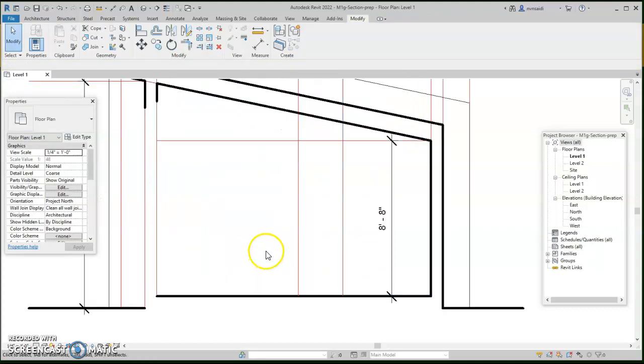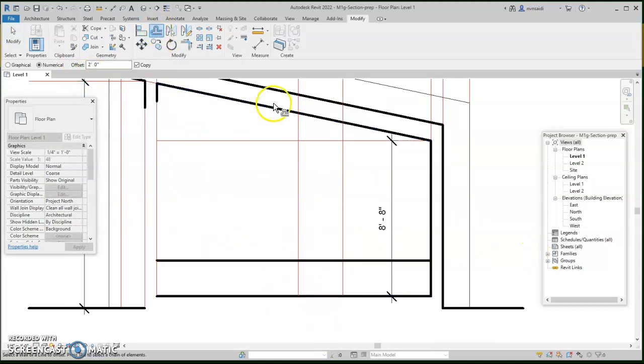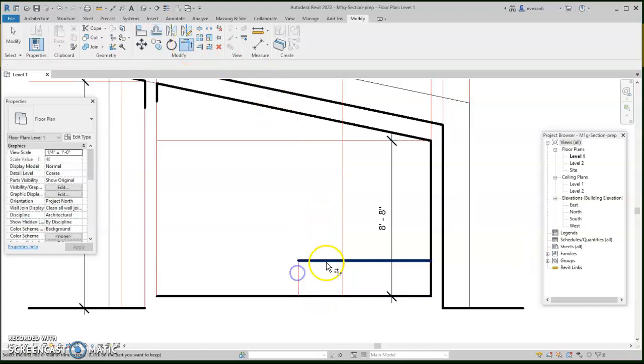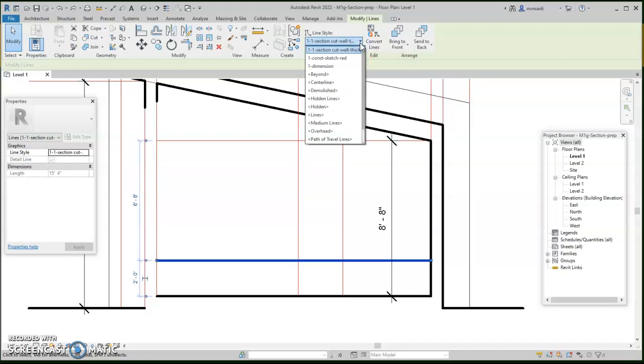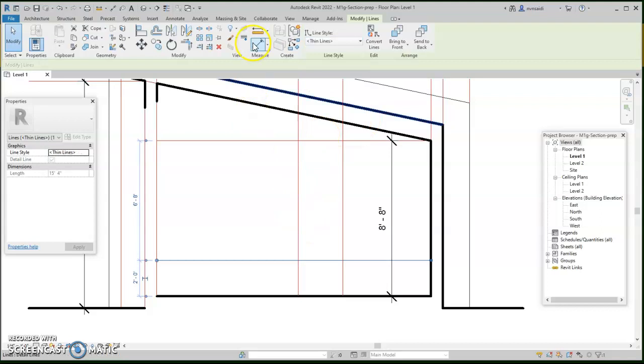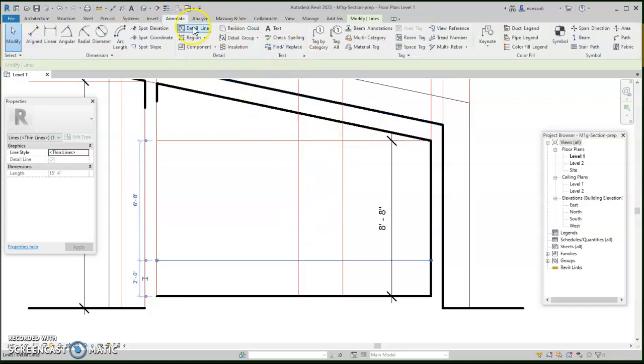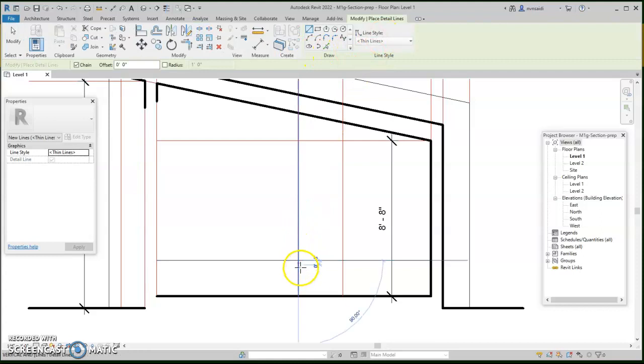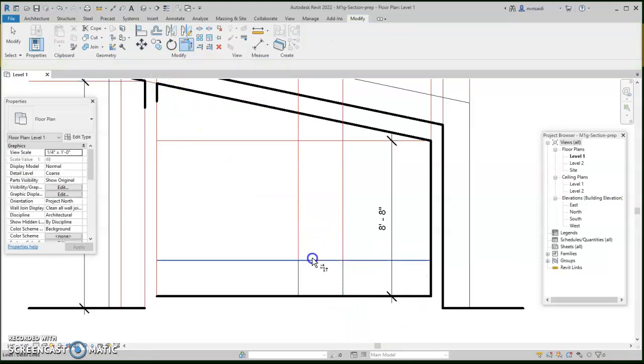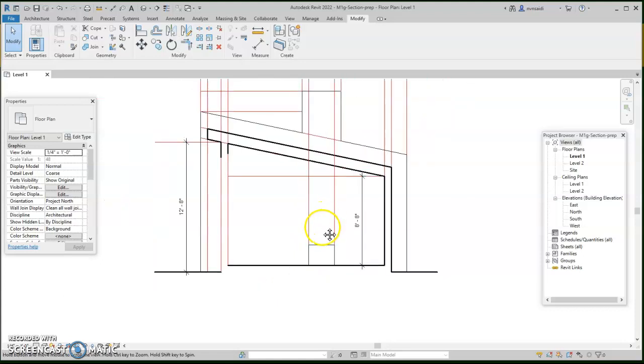That's the fireplace opening. How tall is it? It's 2 feet. So I'm going to go up 2 feet, quickly trim, there, oops, and I'd rather not do it that way. I'd rather first put this as a thin line, so I'm going to convert it into a thin line. Watch how I'm going to go down, thin line. Then I'm going to continue with that thin line, make sure it's thin line, and I'm going to draw my line from there to there, here to there. That's my outline. I can chamfer this in that format. That's the interior of my fireplace.